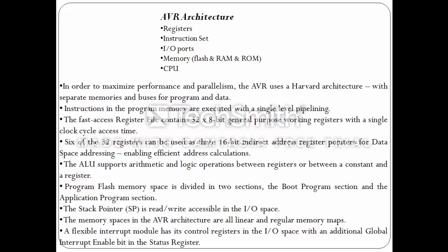The stack is mainly used for storing temporary data, for storing local variables, and for storing the return address after interrupts and subroutines. The stack is effectively allocated in the general data SRAM, and consequently the stack size is only limited by the total SRAM size and the usage of SRAM. The stack pointer register always points to the top of the stack.